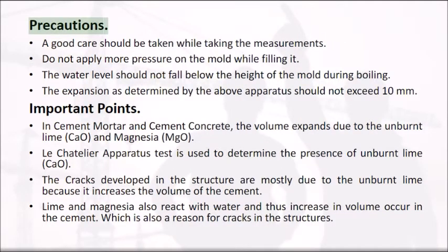Precautions. A good care should be taken while taking the measurements. Do not apply more pressure on the mold while filling it. The water level should not fall below the height of the mold during boiling. The expansion as determined by the above apparatus should not exceed 10 mm. Important points.